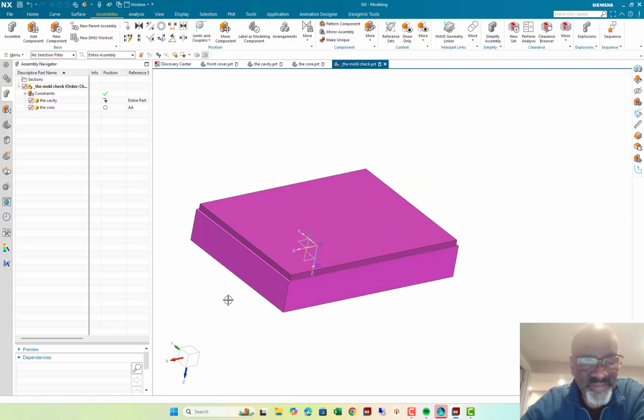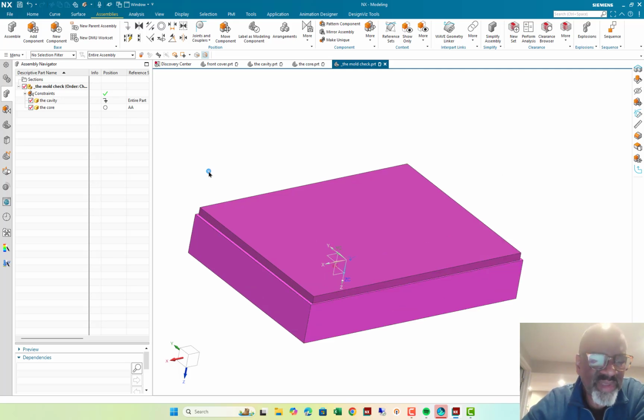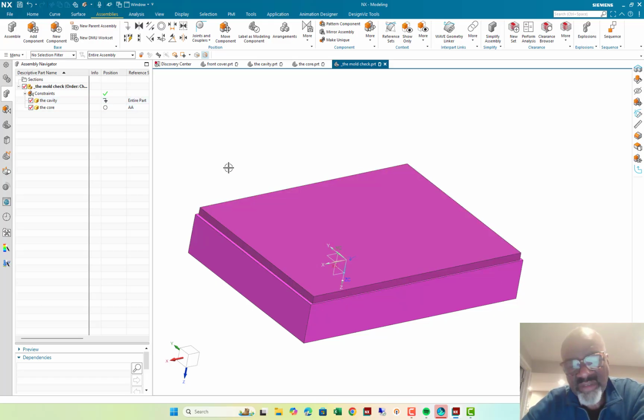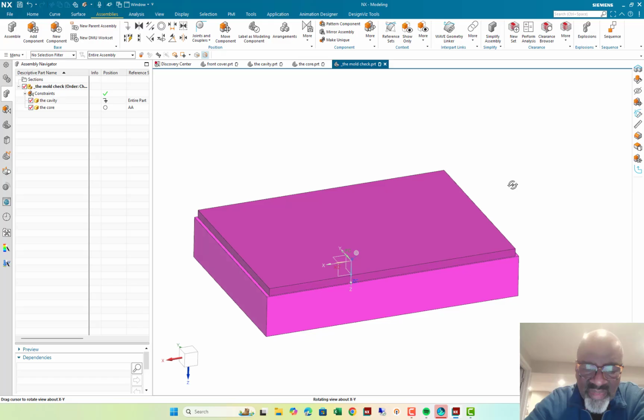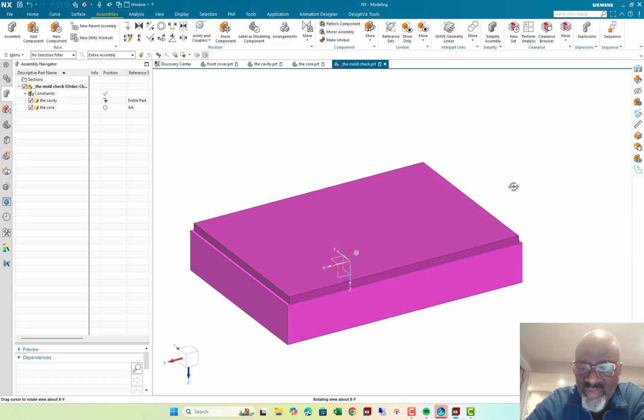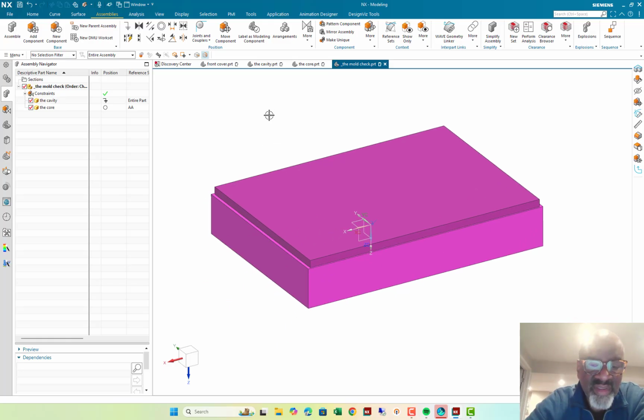So now, if everything is working, I should be able to wave geometry link these pieces of geometry into this mold check, make a block, subtract these two entities from that block, and I should have the perfect housing. Isn't that right? Good. Yeah, let's do that.